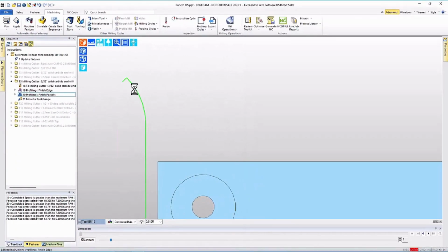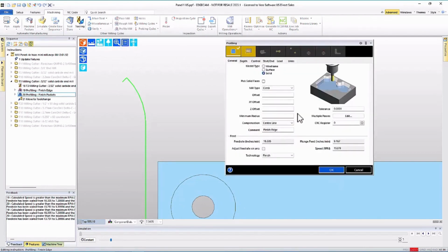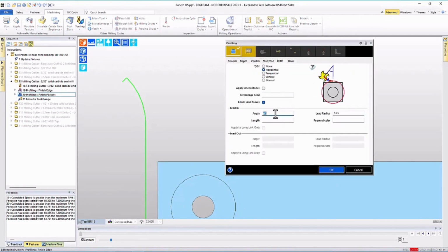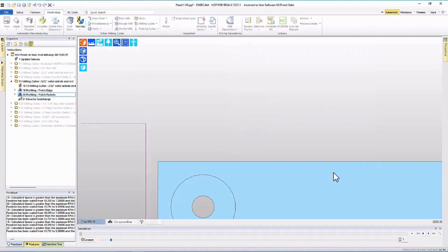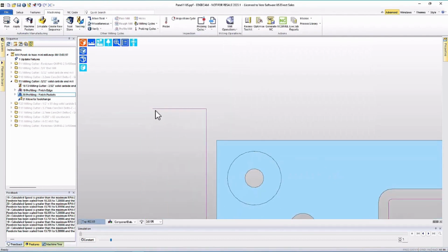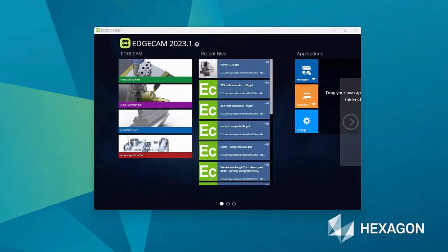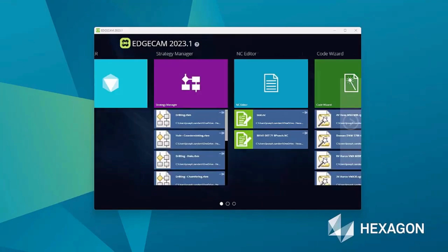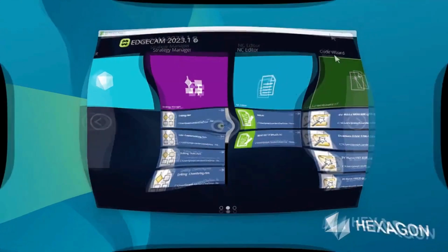If we go back to EDGECAM, edit the tool path, and modify the lead move so that now we remove the radius request, and instead just ask for a perpendicular move of 1/4 inch, notice that there's a perpendicular move with no further perpendicular run-on from there. So what we see happening is that the auto lead moves are built with consideration of cutter comp rules. We need to open the post processor to see what establishes the length of the auto lead move.